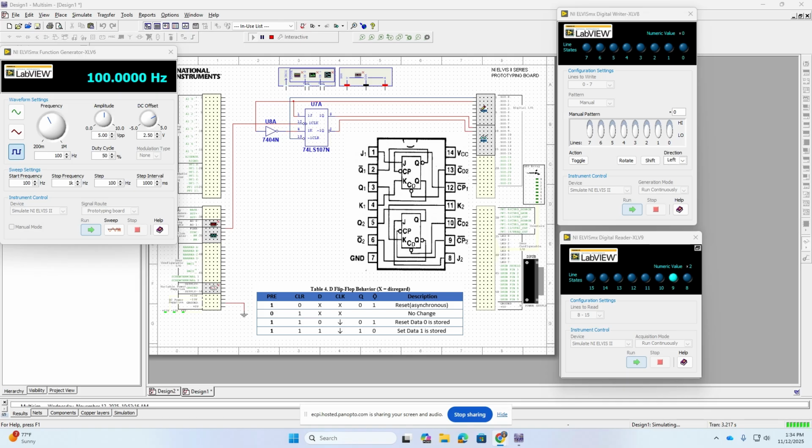Now, in the image, they're using a 74LS107N. Nowhere have they said to switch over to this, so I went ahead and created the demo with this chip. Otherwise, they meant to use a 74LS76. So the 74LS107 is not a D flip-flop. Neither is the 74LS76, right? So the 107 and 76 are neither, but you can convert them to operate as a D flip-flop.